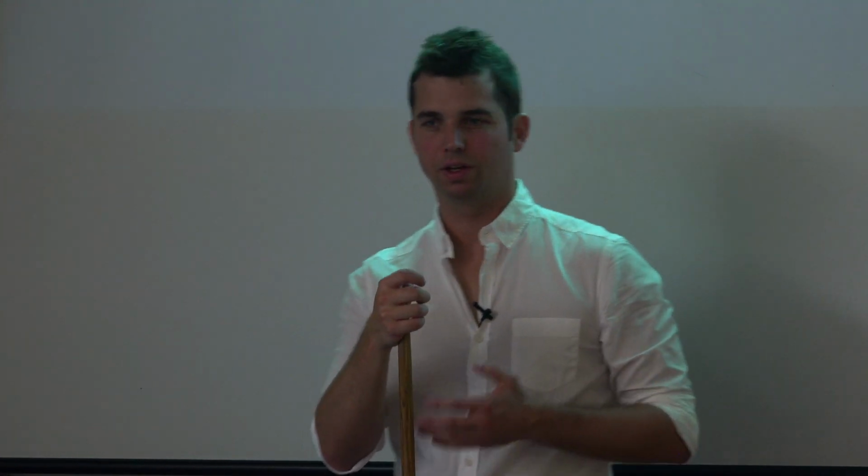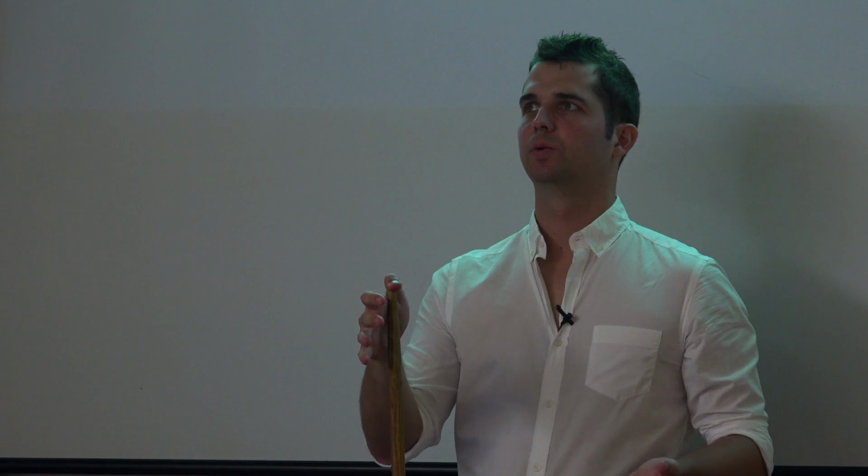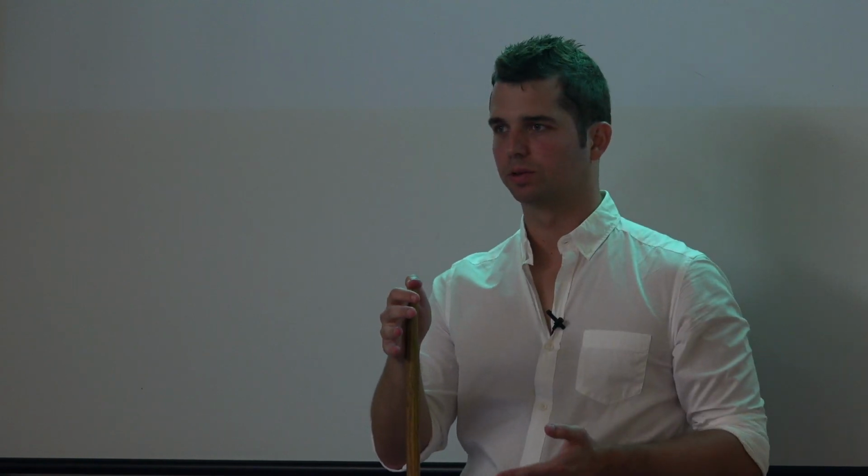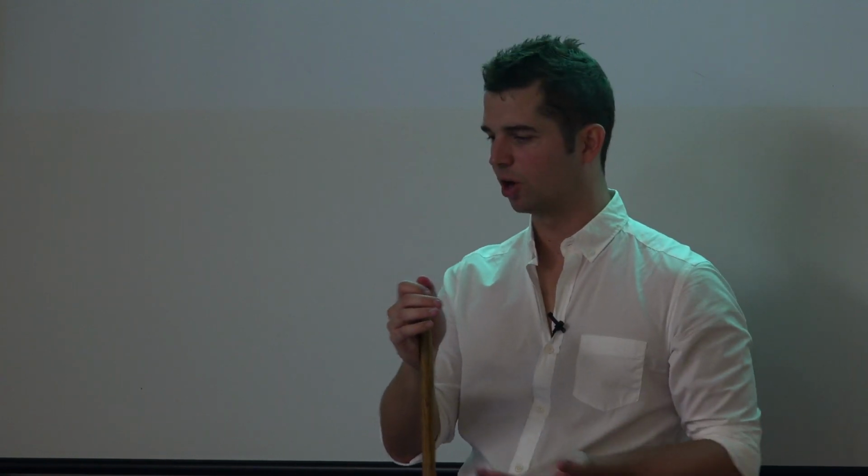So this can be seen as an advantage for people who are trying to achieve linearity in amplifiers, for instance. You have a cascade, and the body effect usually doesn't help. So for FinFETs, as you don't have body effect, it helps. It can also be seen as a disadvantage for those who are trying to achieve calibration through body effect.